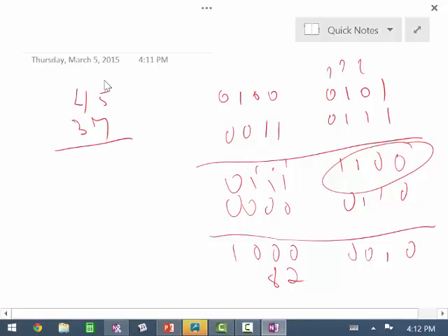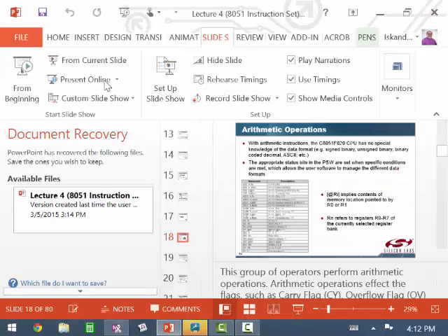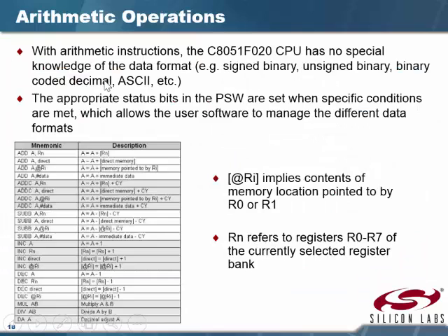So that's what that command does. It also does it if there's a carry. That particular command is used to do an adjust. It's DA space A. I keep seeing DAA because I'm used to seeing some processors, they don't have the space there. It's just DAA and only works on the accumulator right there. But that does the decimal adjust. And what that does is adjust for the fact that you had an illegal BCD number. So that's what that instruction does.